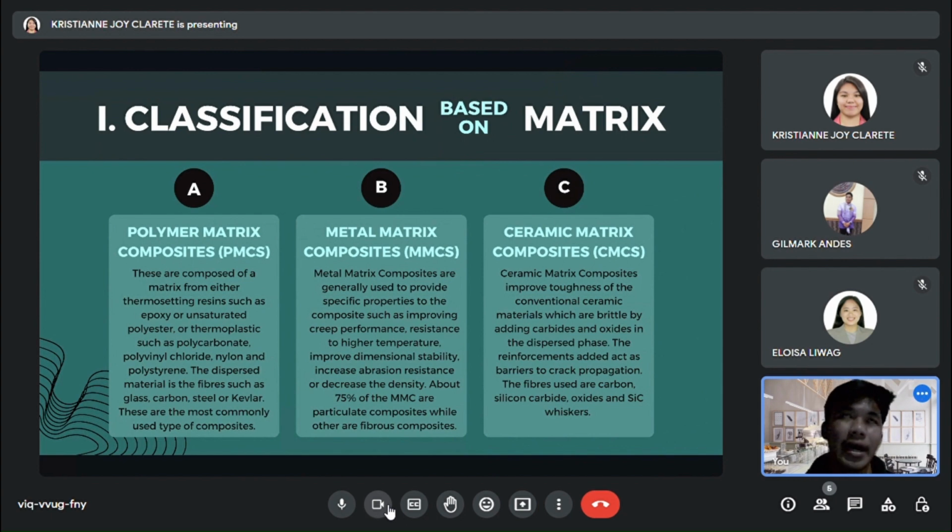So thermoplastics currently represent a relatively small part of the PMC's industry. They are typically supplied as non-reactive solids, or we should say no chemical reaction occurs during processing, and require only heat and pressure to form the finished part. Unlike the thermosets, the thermoplastics can usually be reheated and reformed into another shape if desired.